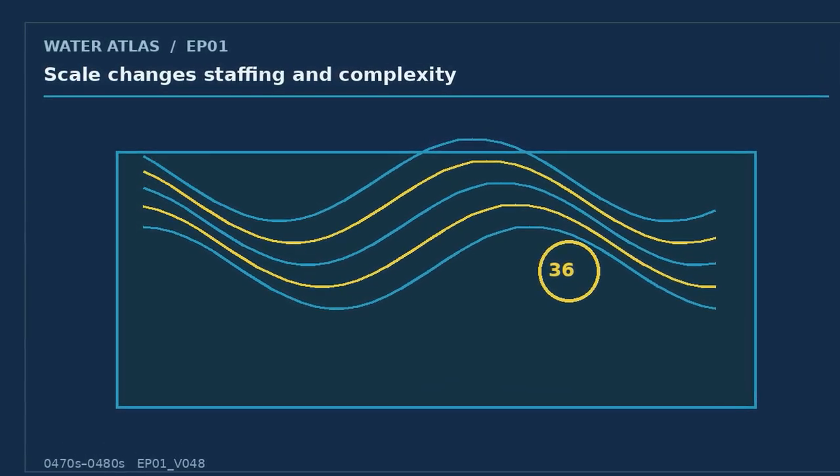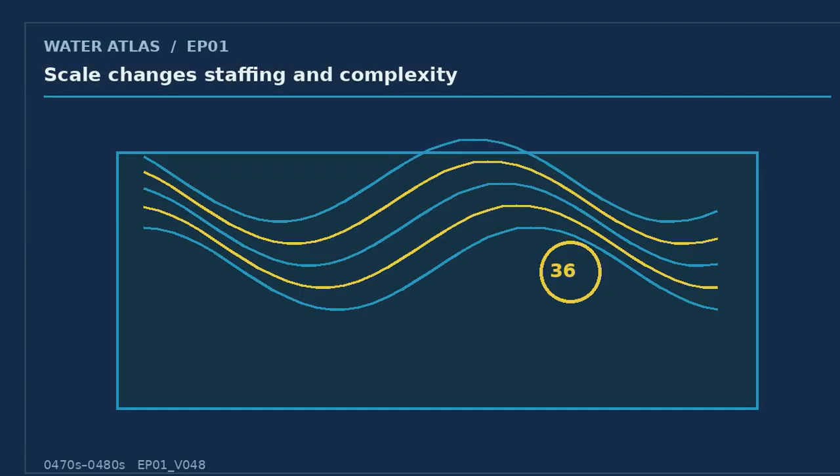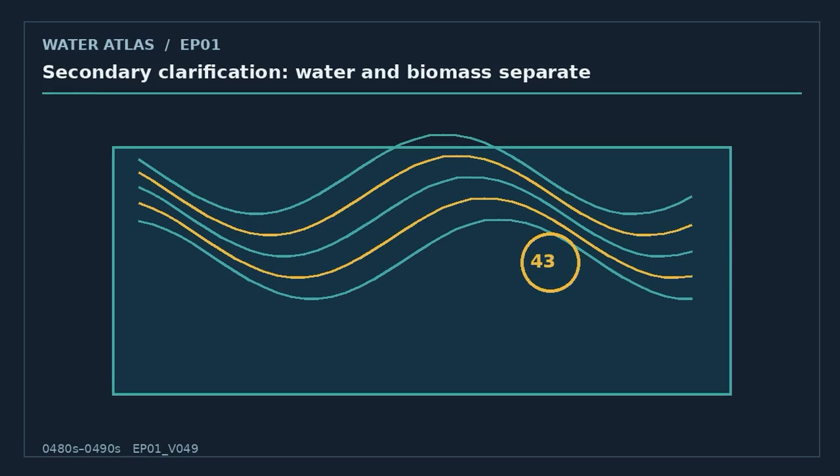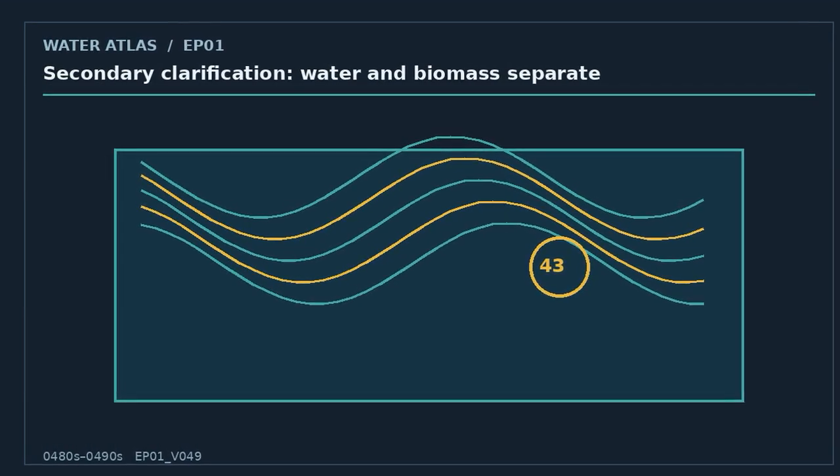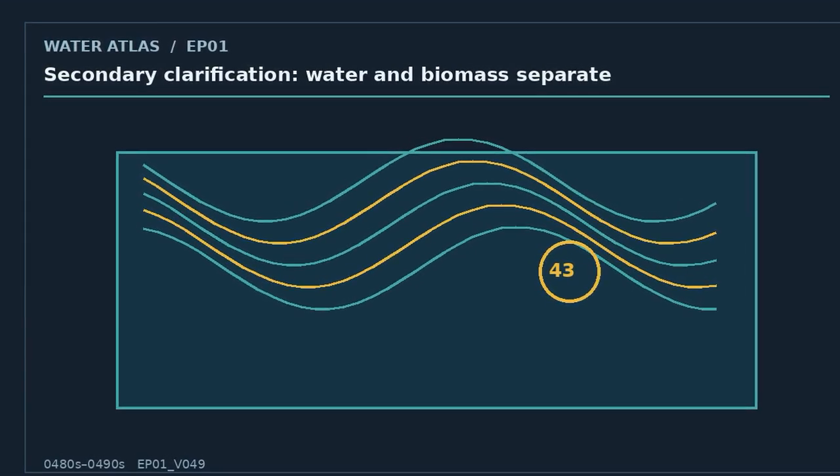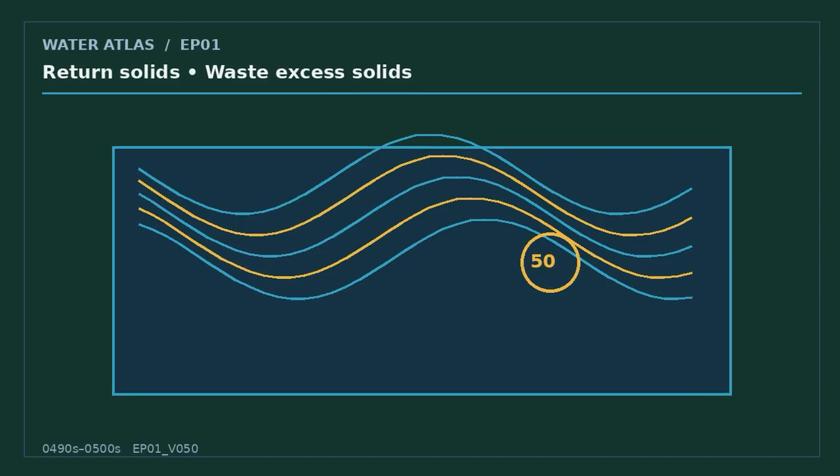In a reuse system, the engineering question becomes exposure management. Who can contact the water? Could aerosols form? Could cross-connections occur? Is storage protected? Are pipes clearly identified? Are online instruments calibrated? Is there a response plan if quality moves out of range?